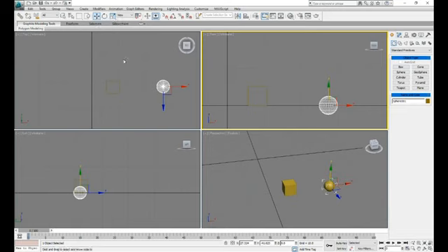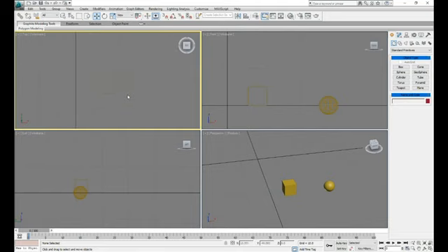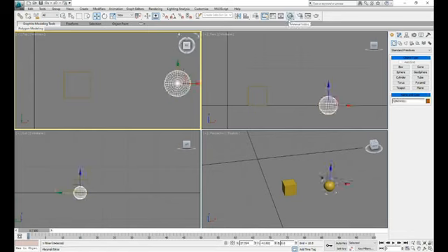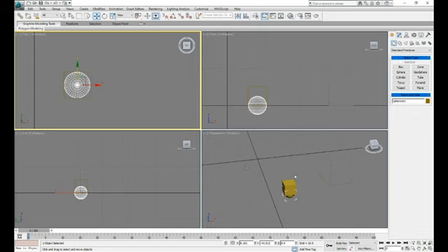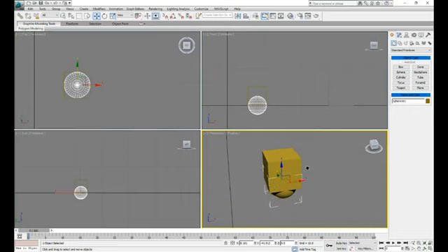How to do this one accurately? So what's closer here on the top? What should I do? Select the sphere. What are the things that I will do? I will choose this one, align. I will click here. Then I will remove Z. I will go to center, center, okay. Now, if you can see in the perspective, this is what happened. It is in the center, but inside.